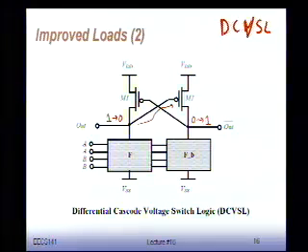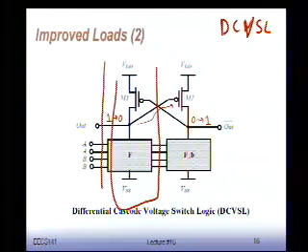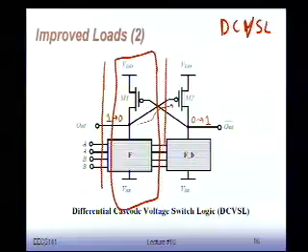Now, what this does is the following. Suppose I have available at my inputs not only my normal inputs, but also the inverted values. The inputs are complementary. When I have A, I have A bar. When I have B, I have B bar. That's why we call it differential. You always have, for every single input, the single and the inverted. This structure here, we know. If I would ground this, it is a pseudo NMOS inverter: a logic network and a PMOS network grounded on the top. This network is the same.